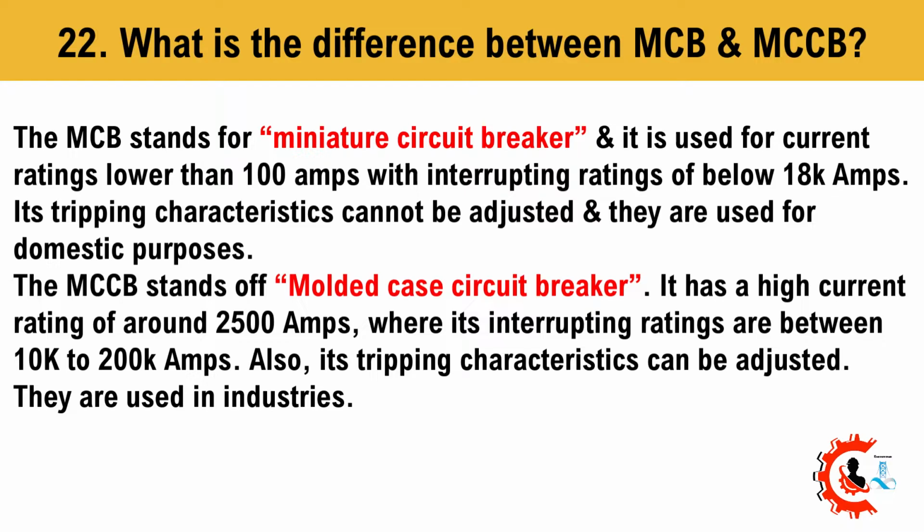The MCCB stands for molded case circuit breaker. It has a high current rating of around 2500 amperes, where its interrupting ratings are between 10 kA to 200 kA. Also, its tripping characteristics can be adjusted. They are used in industries.